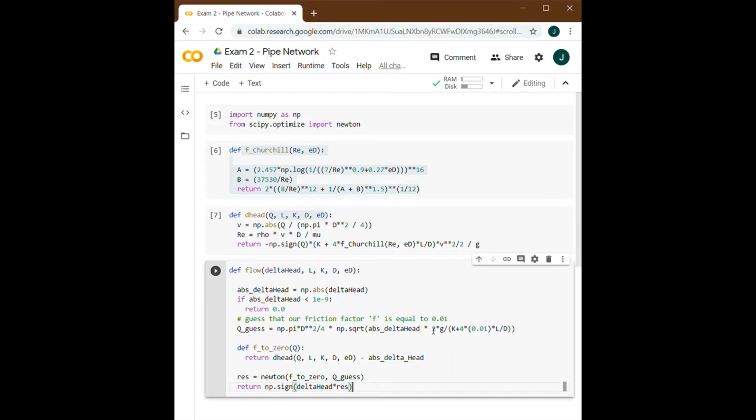So for example, from here, we could say that this pipe from node 1 to node 2, we're assuming it's flowing from 1 to 2. However, if we calculate here and get a negative sign, that means we were wrong in that assumption, and it's actually going from 2 to 1. So that's what the negative sign is, and we just removed it to make our calculations easier.